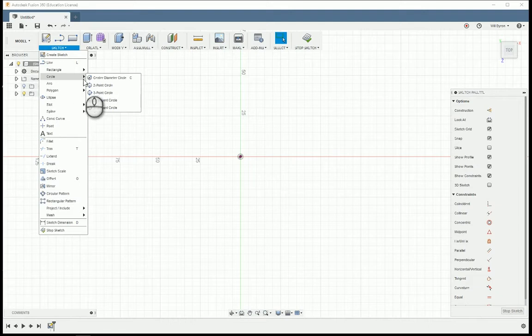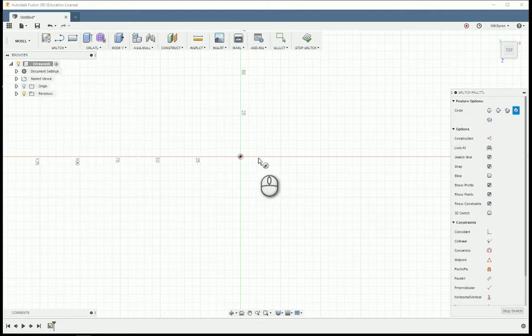Circle tool, also the same. I chose center point radius. That's my tool of choice. Doesn't really matter. Grand scheme of things, doesn't mean a whole lot. Again, tab here doesn't do anything because there's only one numerical value that you can input to affect the circle. Once you hit enter once, it locks it. When you see that lock, it means you've actually dimensioned it.